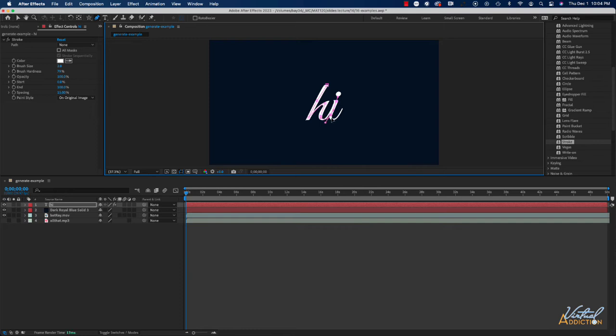That's going to make this effect work a little bit better. I'll lay down my next point. If you want to break the handles at all and turn around their direction, you're going to hit your Option key or Alt key, and that will allow you to break the handles.